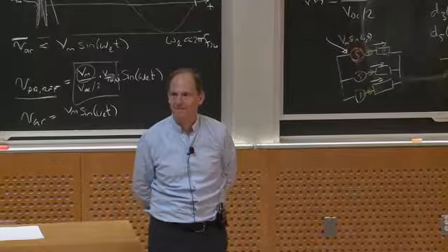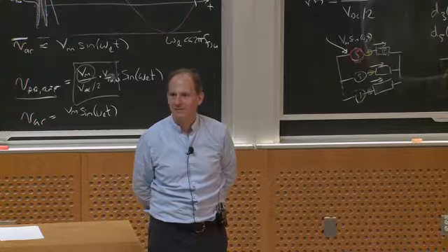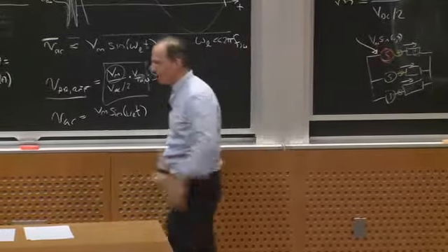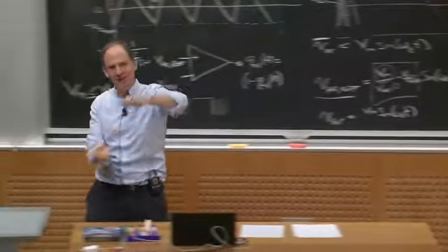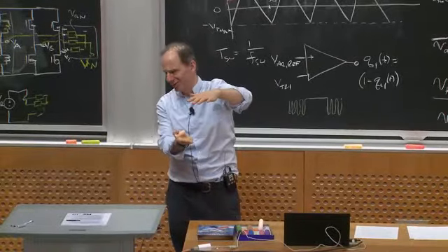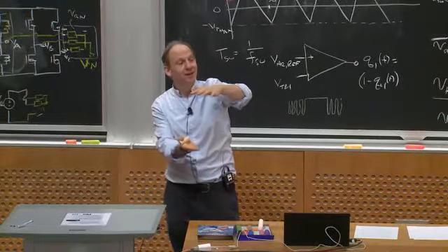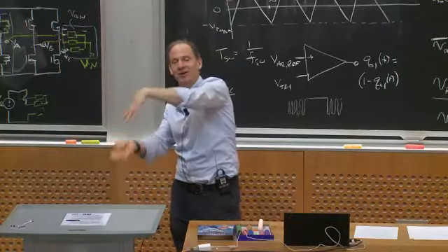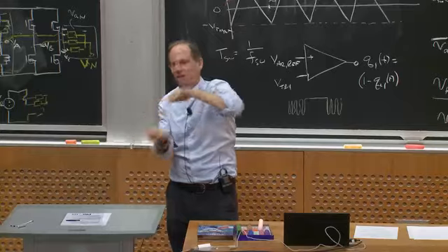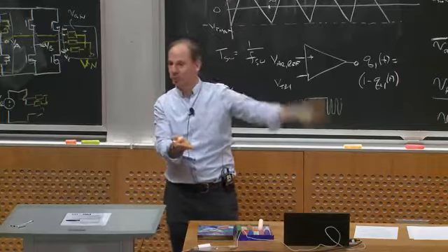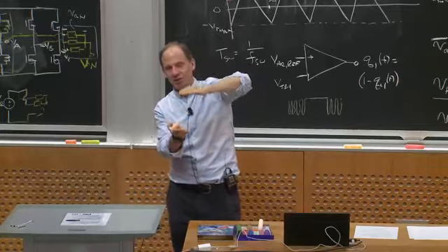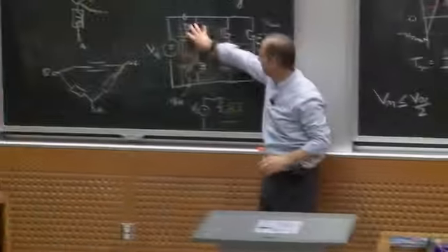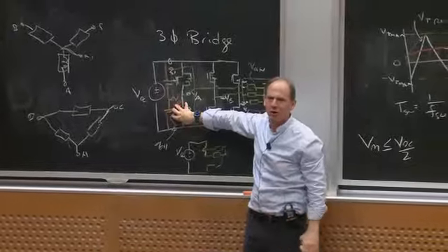Is it possible to step up VDC with a boost stage before? Absolutely, and in fact, that's what people do. So why is this a concern? Because in a Prius, you have this bus voltage, which is your battery voltage, and it might vary over some range, and you're trying to deal with a motor whose back EMF varies over some range, and you need to drive it. If you don't like that, you put another stage in between your battery and your converter, and you can control the DC bus voltage to go higher, and then you're only limited by how high a voltage these switches can handle. So you're always limited by that.